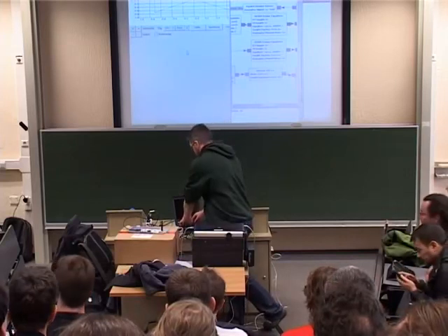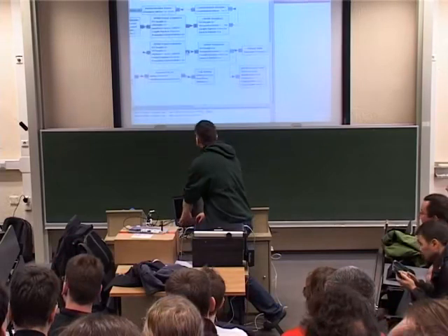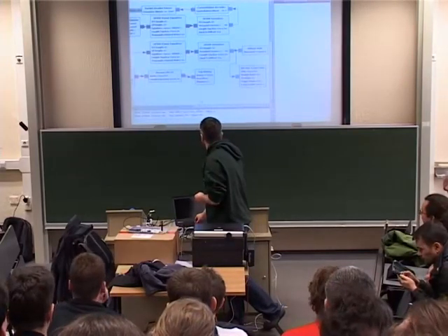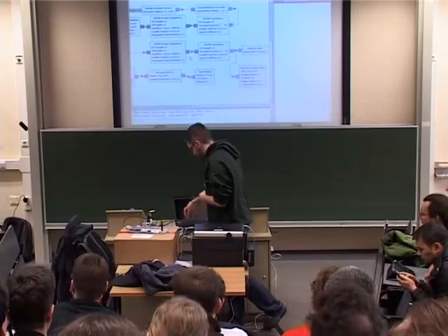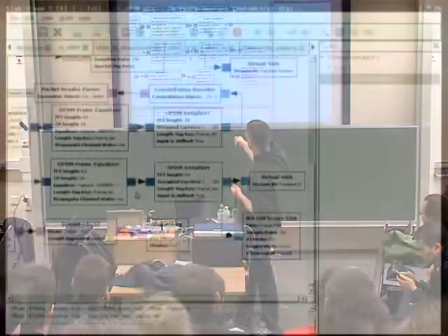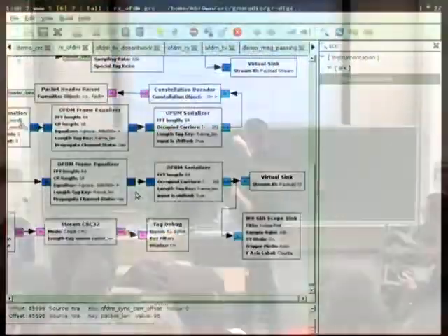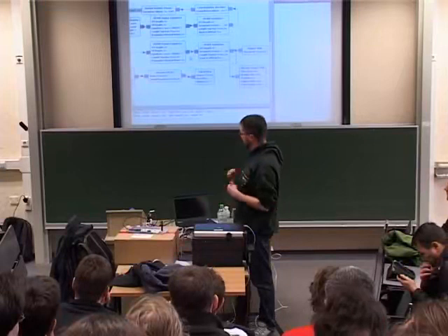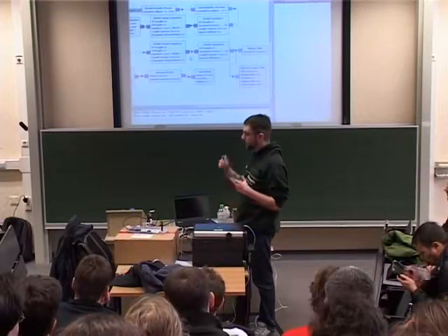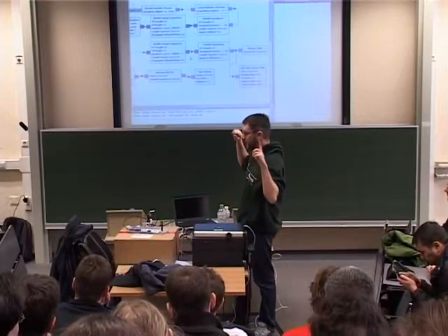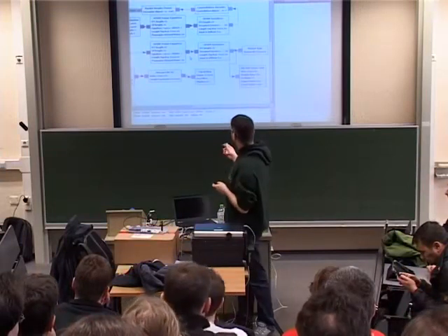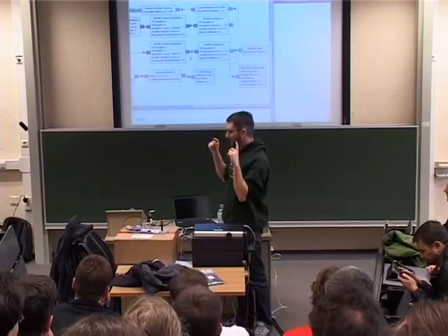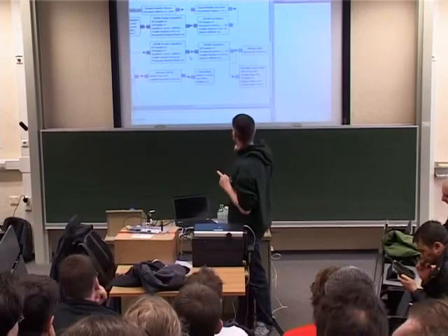How do you actually extract a single subcarrier? It's actually not. That's all subcarriers being serialized. You can see the difference of color here and here. Dark blue means I'm operating on vectors, and in this case, one vector is always one OFDM symbol. So you get the time frequency plane. You operate on that. Eventually, you'll need some block that knows where the actual payload data is and picks it out, and that's what the serializer does.